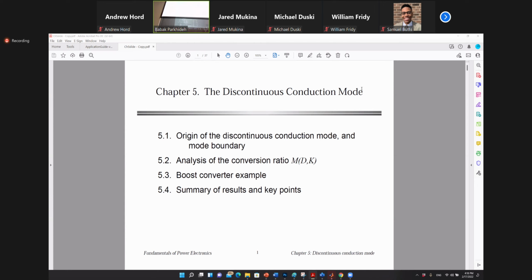No, but in practice, if you remember from previous design, you have a dead time. You have shoot-through protection for the dead time. In other words, you want to guarantee that these two switches are never turned on simultaneously.